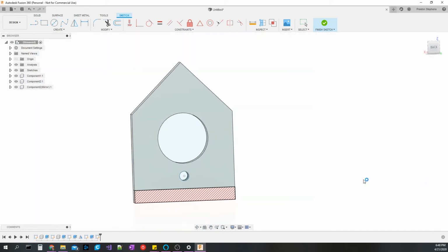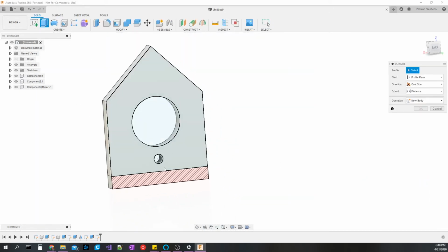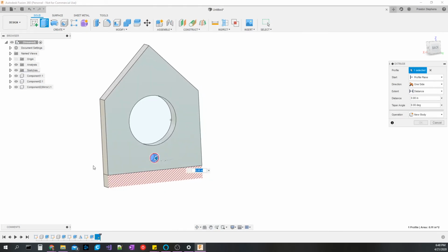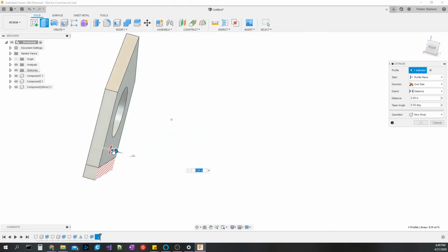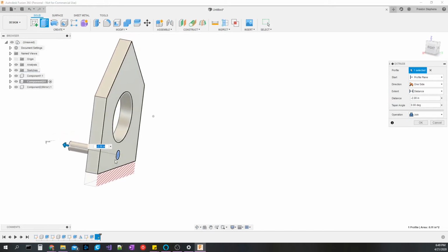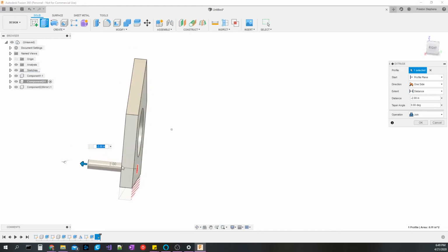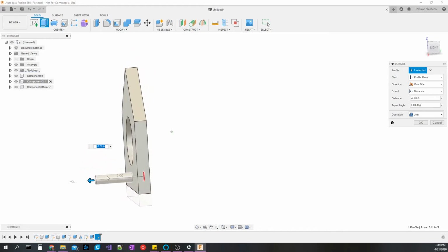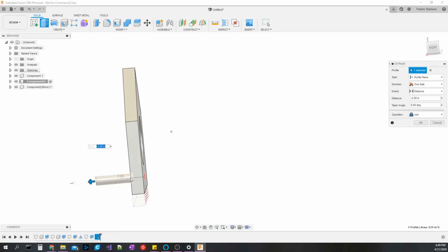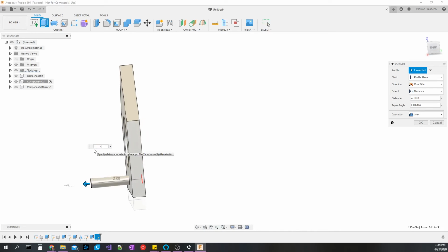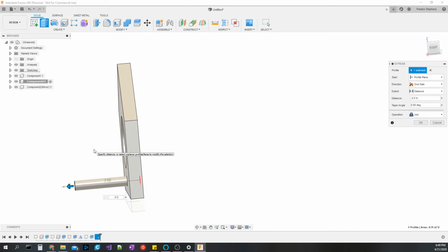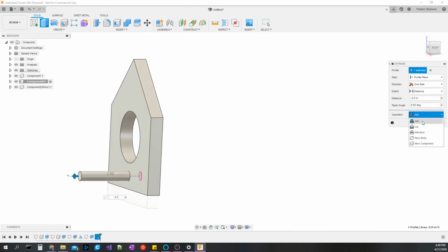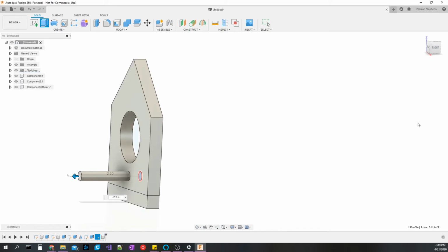Just like that. Finish sketch, and then come over here to extrude. We're going to click on the extrude, and we're going to pull it this way. So see how it's negative? Because from this original plane, it was over here. And so now, this length is only 1.5 inches out. So we want to go negative 2.5 because we want 2 inches sticking out for the birds to stand on. But we need to choose a new operation, a new component, because it's the perch.